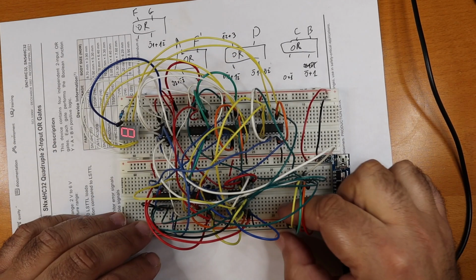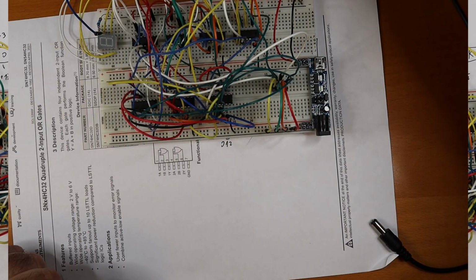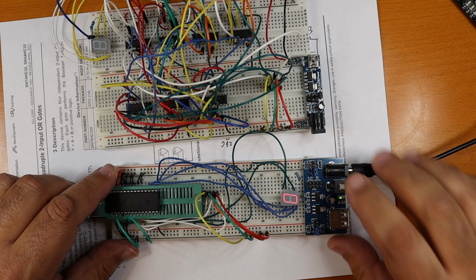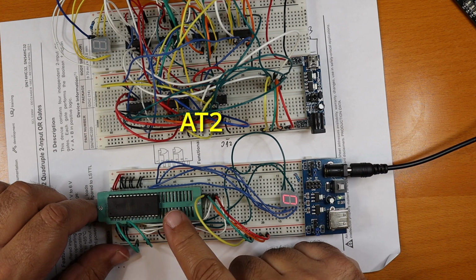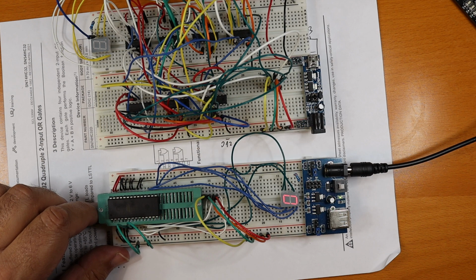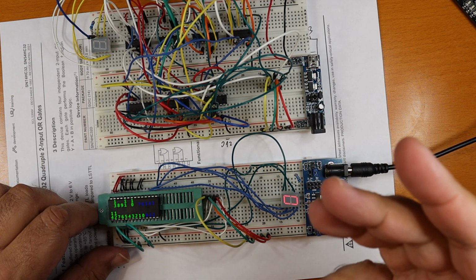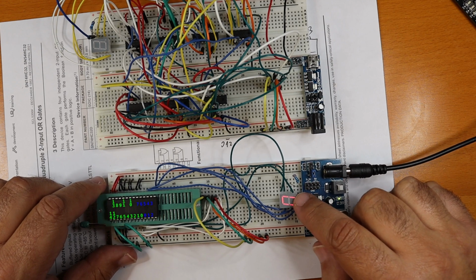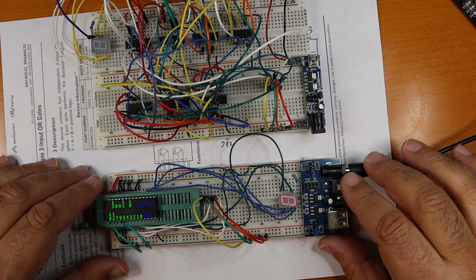But either way, we have a working 7-segment decoder here. But there's another way to do that. That other way, and you can see it's much, much simpler, is to use a ROM chip. So this is the AT28C256. It's a 32 kilobyte ROM, which means it has 15 address lines as inputs and 8 data bits as output. 7 of those data bits are hooked up to the 7-segment display. You see, this is a much, much simpler setup.